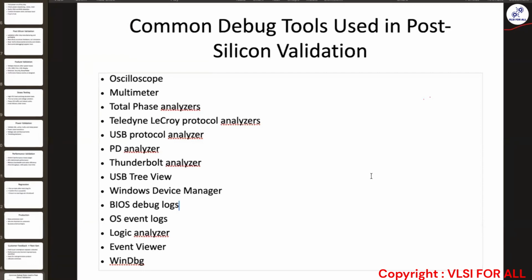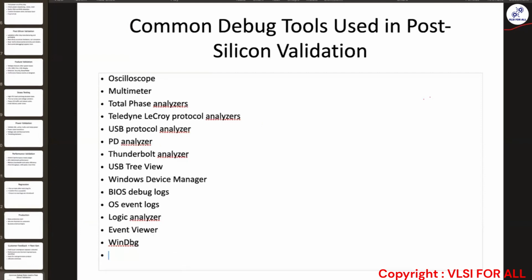Yeah, I can add one more thing. So one more thing is JTAG. With the help of JTAG, you can actually probe, or you can access the internal registers inside your CPU. It is more like an interface. You connect it to your system, and the other end would be on your reference board.